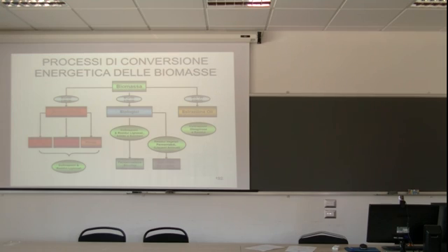But I worked on an alloy project back in New York, and we did corrosion testing at temperatures ranging from 150 degrees Celsius to 1000, in different conditions, from wet to high temperature, high corrosive salt to dry, just reduction, oxidation, all kinds of tests. And I came across some alloys in the category of 316 steel, with the composition slightly altered, but they perform really nicely.